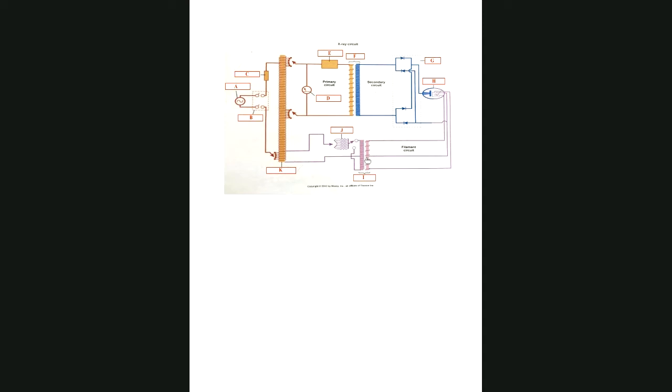So we have to have a sufficient kV to pull all the available electrons across. But that's the only way it ever affects quantity. If I use too low a kV, some of those electrons will just be left sitting at the filament. So that's the only impact on quantity that kV has.